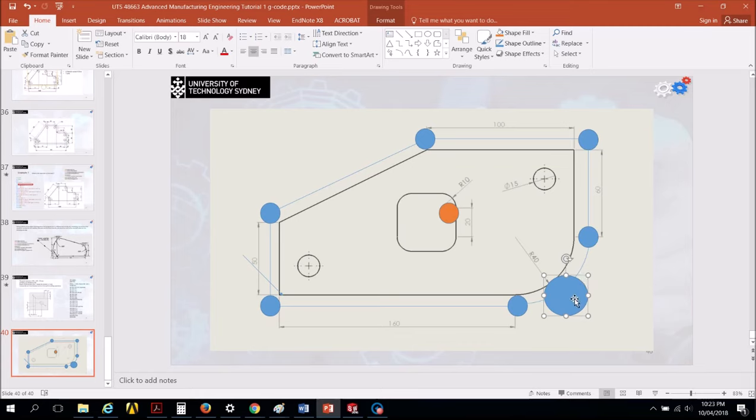Then I have to take it up by a distance equal to the diameter of the cutting tool, stop here, then go back all the way to here. Half of the cutting tool in, the other half out. Then go with a Y value equal to the diameter of the cutting tool, go back once again, up, back, until I get to remove the part I would like to remove. Okay, so we covered everything.